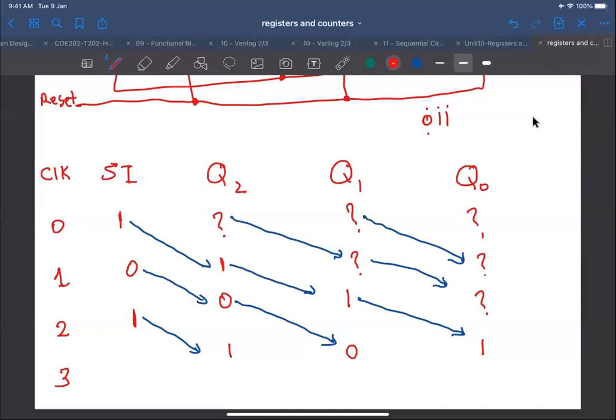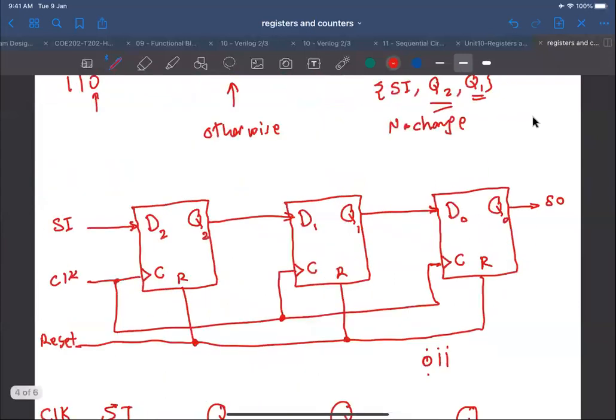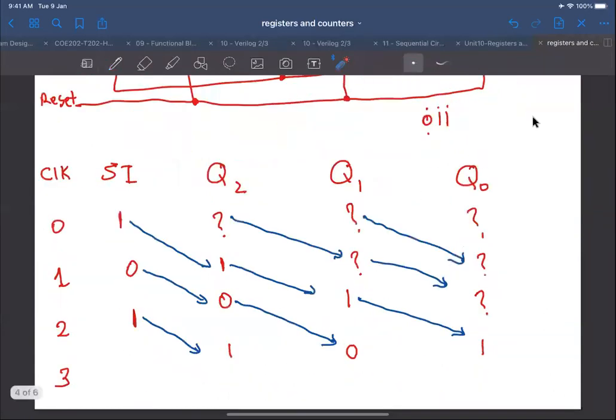Yes. You start from the least significant bit and then shift them one by one, because basically you can see that the final destination here is the least significant bit. So you should input the least significant bit first and then the most significant bit last, okay? So if you have, for example, a 5-bit register, how many clock cycles do you need to load something in it? 5 cycles, basically, okay? It's the same number of bits, okay?